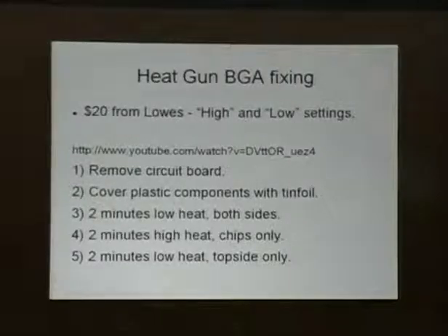You don't want to be melting your connectors and your memory sockets and whatnot. 2 minutes on low heat, both sides. You want to warm that whole PCB up. You don't want to introduce any thermal shock. Once it's warm, you focus high heat on the chips for 2 minutes. Just really blast those things, get them nice and hot.